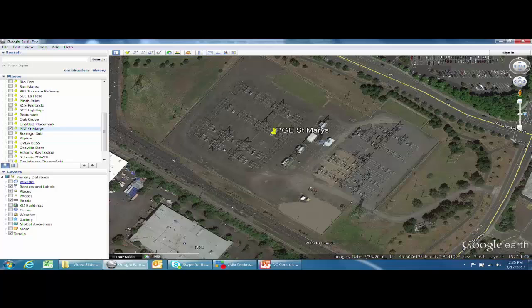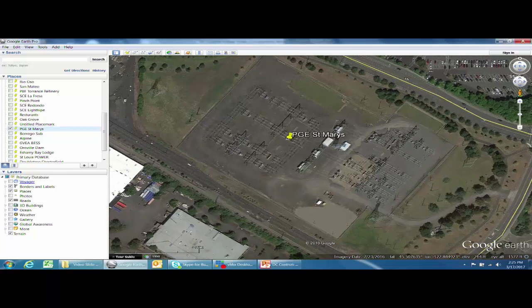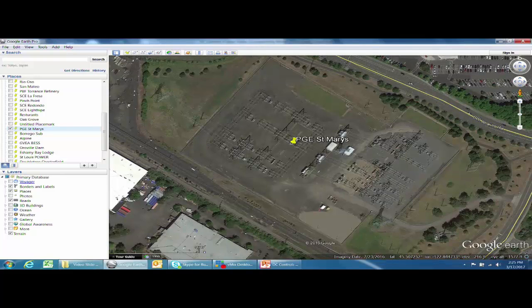And on this side you have a couple rows of breaker and a half, although on the last two there are breakers missing, so you really just have double bus, double breaker. But anyhow, we were converting this substation from its old configuration, which was a main and transfer scheme that dated back to the early 50s.